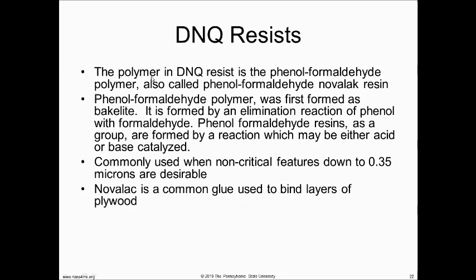And these DNQ resins are really good down to about 0.35 microns. And really in lithography, i-line in a contact aligner, which is my discussion for today, that's probably for microtechnology like 0.35 microns. It's sub-micron because it's less than 1 micron. But that's probably really cost effective, and the machines are $100,000 or $200,000 or $300,000. And that's probably the cheapest entry into advanced lithography that we can get.